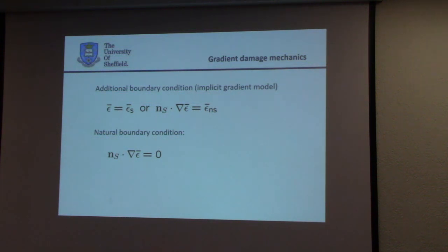Now, in practice, it's not such a big issue, because according to the Saint-Venant principle, these kinds of things have short-range influences. So unless your problems are close to the boundary, they will not have much influence. But it is an issue and you have to be aware of it. There's no good solution available.